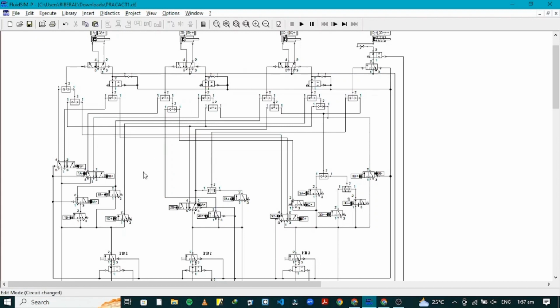Hence, actuator B will start to retract. Meanwhile, to actuate actuator C, we connected a three-way valve to the actuation side of actuator C. This valve is initially open, and it closes only once B is actuated, as with the label 1B++. It also has a spring connected on its right so that it retracts immediately and loses supply, since in the next sequence it needs to retract.